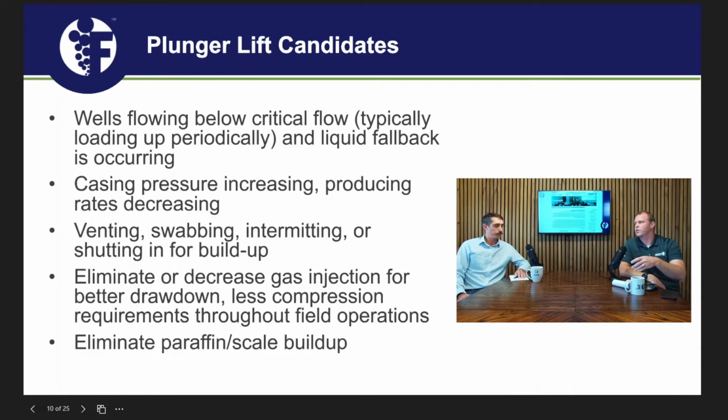Because the plunger is essentially wiping the tube walls. You mentioned a pig earlier, right? So it's clearing that paraffin or scale buildup. And for me, the last 13 years almost has been spent primarily in the Eagleford, but some other South Texas plays too. And some of that Eagleford stuff, our initial reasoning was strictly to put it on gas lift wells because paraffin can be an issue there. And from that is where we started seeing the other benefits of decreased injection and even lower flow and bottom hole pressure. Okay, good to know. Yeah, and we'll talk about that.